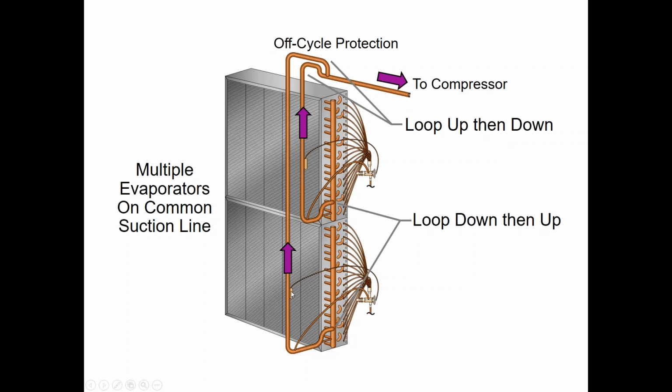Okay, so we should always be in this position so the liquid refrigerant in the sensing bulb can boil off in a vapor state and allow pressure change back to the power element that way. So think about how the bulb's mounted on the line. If it's a vertical pipe, obviously, it doesn't matter what side you put it on the pipe, but it does matter where you put it in relation to the suction header. So basically the rule of thumb for a TXV sensing bulb is 2 90-degree elbows away from the suction header.